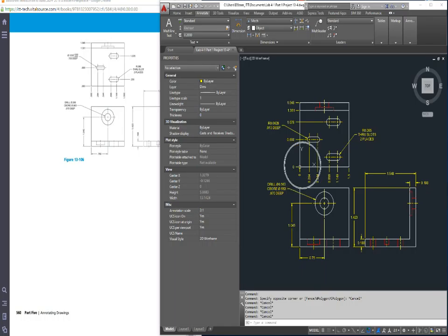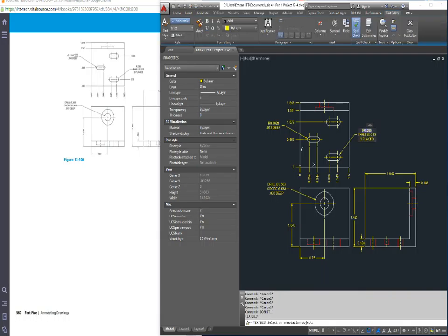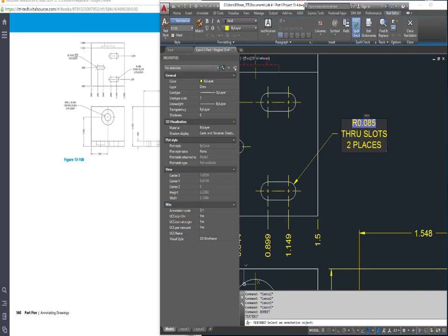Okay, so I have all my dimensions on there. This is my new 0,0 point, so I can do those ordinate dimensions. I've used the dimension radius command because this is a partial circle. I'll dimension it as a radius right here. All partial circles will be dimensioned as a radius. And if I DDEDIT my dimension, you'll see there's a field in there that you don't want to ever change if you can help it.